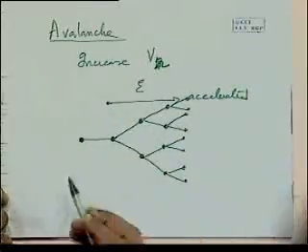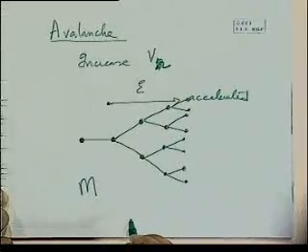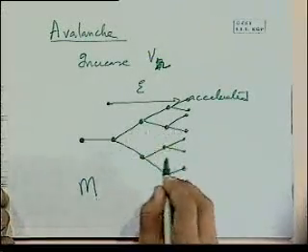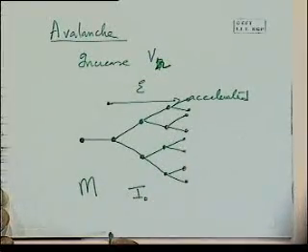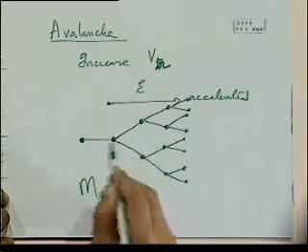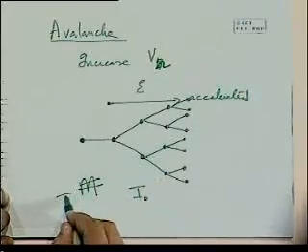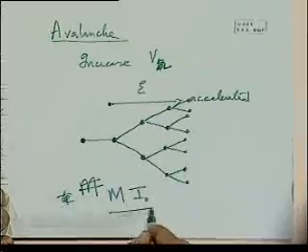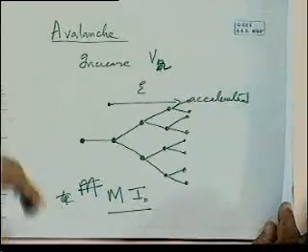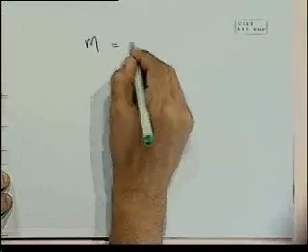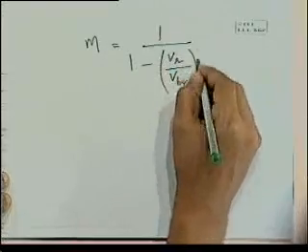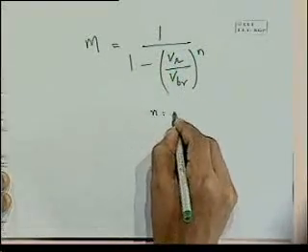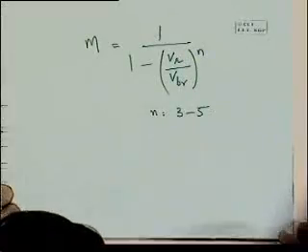So all of a sudden now we've got so many electrons, and that is really what is happening in avalanche breakdown. There's one term called multiplication, which means that if under reverse bias conditions where you did not have this breakdown, the current was I0, then under reverse breakdown conditions where we have avalanche breakdown, the current has been multiplied by this term M. So it's a multiplicative effect, where M is given by 1 minus VR by V breakdown to the power of an exponent n, where n can vary between 3 and 5.